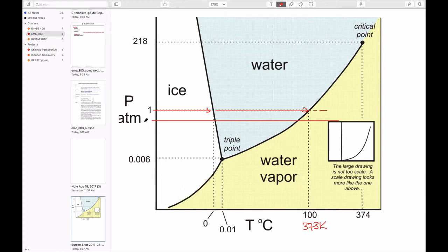It'll be less than 1 atmosphere, because all the air that sits on top of us now, which is so heavy on us, which makes 100 kilopascals stress at this level, isn't above us at that elevation. So the pressure is lower. If the pressure is lower, then the temperature at which water boils is also reduced, and we can use tables to figure that out. I don't know what this is, but maybe it's 80 degrees centigrade or so.